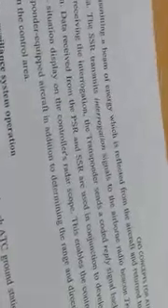The ground-based ATC system works by transmitting a beam of energy which is reflected from the aircraft and returned to the PSR antenna. The SSR gets a reply signal back. Data received from the PSR and SSR are used in conjunction to develop a local air traffic situation display on a controller radar scope.